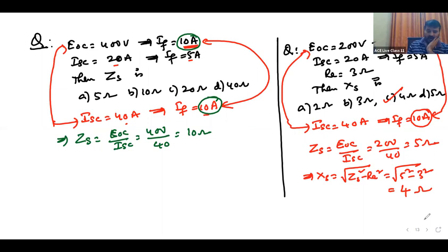When 400 volts at 10 amperes is given, and current is given as 5 amperes, you have to bring current to the voltage. ISC is linear, OCC is not linear. If the voltage is given, IF is equal to 10 amperes at 400. I am not sure that at 5 amperes it is 200 volts. Current can be taken for any value, so always you can shift current, not voltage. Short circuit current of 5 amperes you can bring to 10 amperes. Conversely is not correct. Don't bring.